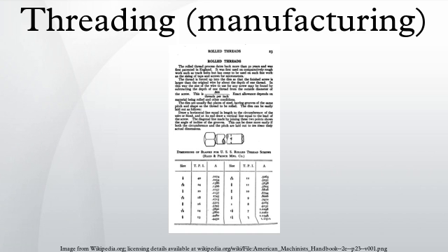For example, thread lapping following thread grinding would fall only on the extreme toolroom end of the spectrum, while thread rolling is a large and diverse area of practice that is used for everything from microlathe lead screws to the cheapest deck screws. Threads of metal fasteners are usually created on a thread rolling machine. They may also be cut with a lathe, tap or die. Rolled threads are stronger than cut threads, with increases of 10% to 20% in tensile strength and possibly more in fatigue resistance and wear resistance.